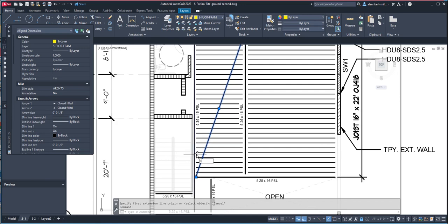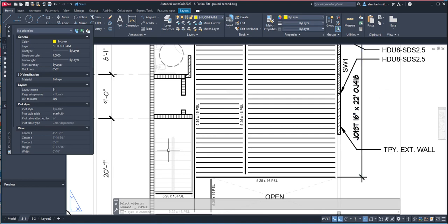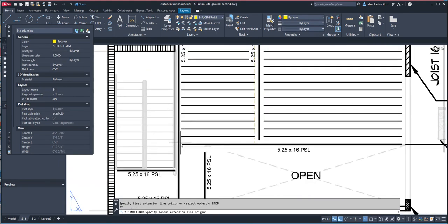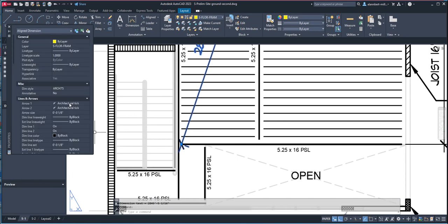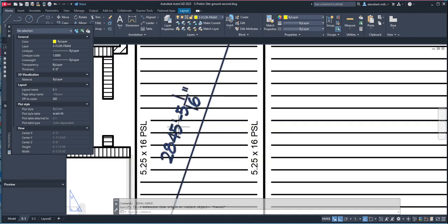And then they wanted to change the arrow size. Oh, I did it again. Erase. This is a double click outside and repeat that thing. I want to do an align. I want to do from endpoint here and to endpoint here. And I click anywhere and then select that and then change to arrow filled or close filled for both ends of the dimension.